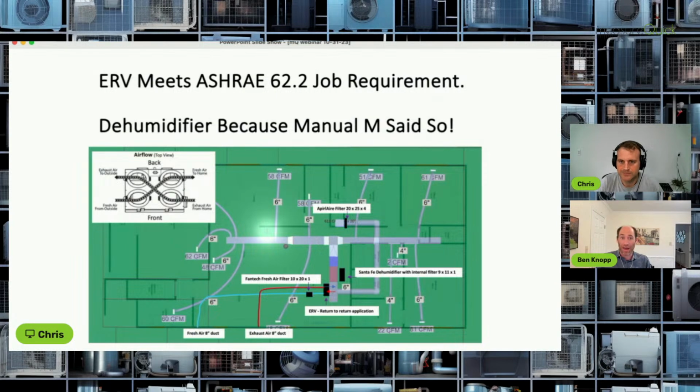We do not want that. With variable speed equipment, we want it running all day on a peak dew point day so that it can remove all that extra water, even though it has less total cooling to do. So that brought us to the second design of this job.